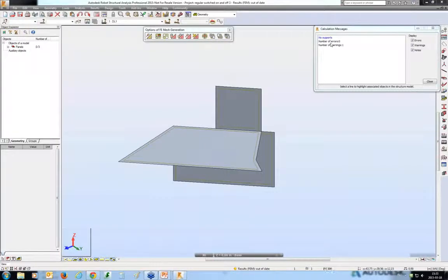So let's see. Sometimes I verify the model and get no mesh problems, and then I try to run calculations, which then brings up incoherencies. And the response was, after playing with meshing or in between, you can run correction to merge generated nodes on edges, or run model generation before running verification. Yeah, if I may add something, that may happen when you use local mesh generation.